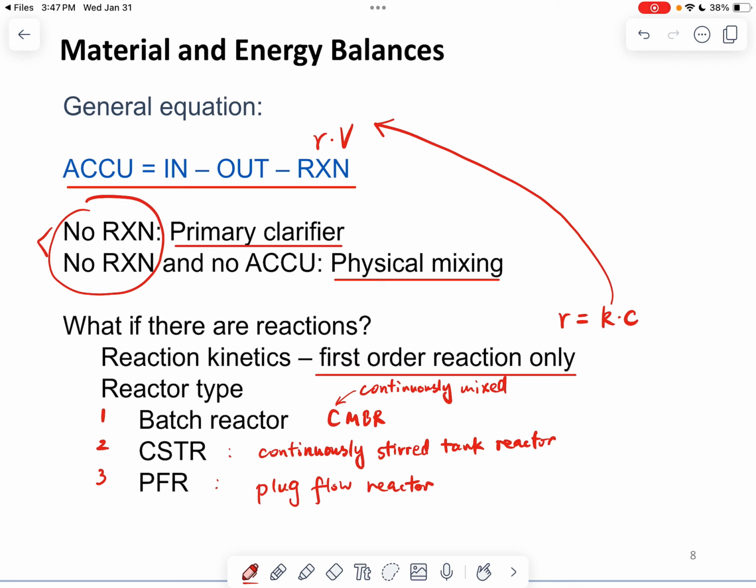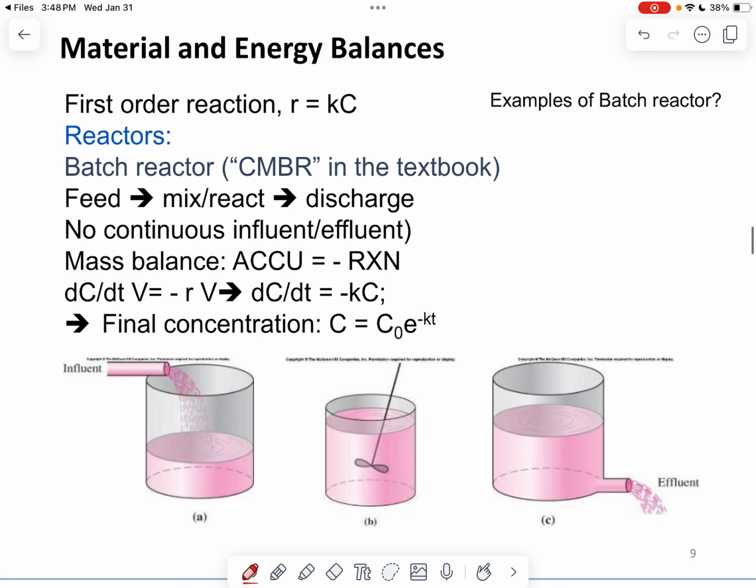You'll find out that we use these different types of generalized reactors in a lot of pollution treatment devices. So first is a batch reactor. As the name sounds, a batch reactor lets the reactions happen in batches. You find a container or reactor first. First, the reactants are introduced into this batch reactor. We can assume that there's no reaction during this pouring process. And then after the solutions are ready, we have a big stirrer that starts to mix all of these reactants and let the reaction happen, right?